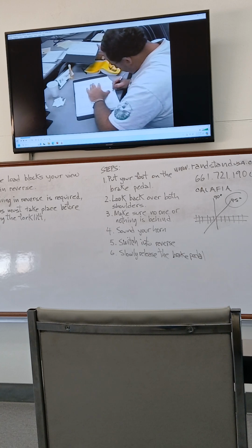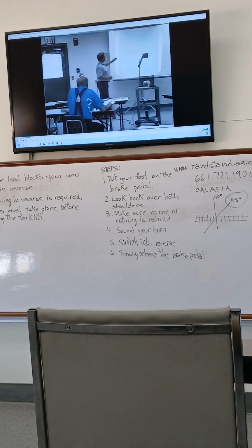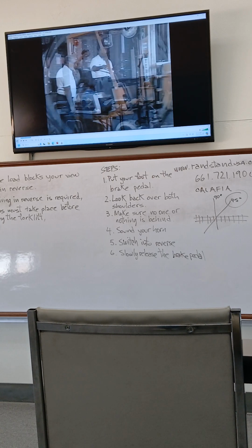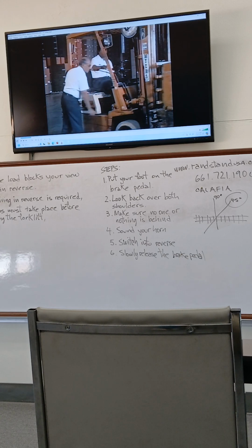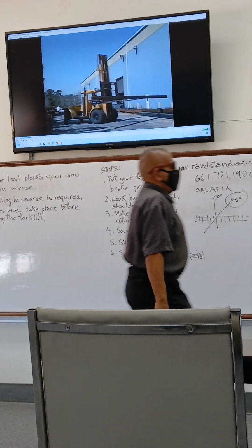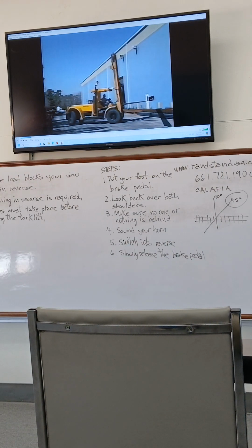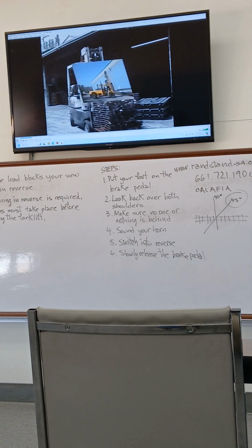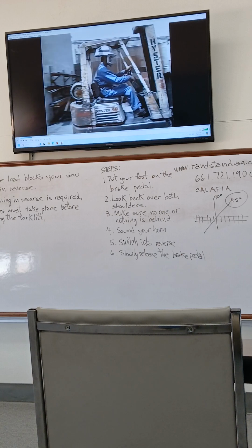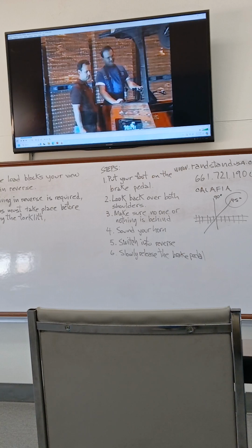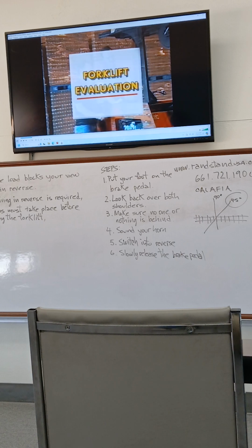First, there's academic or classroom training. This program covers the majority of the required classroom training, but your company amplifies this training by making your training site-specific to your operations. Next, operators must be provided hands-on training to ensure operators fully understand controls, equipment performance, individual characteristics of each forklift equipment they will be operating, and the potential hazards that may be encountered in your work area or organization. The third method of training is evaluation.